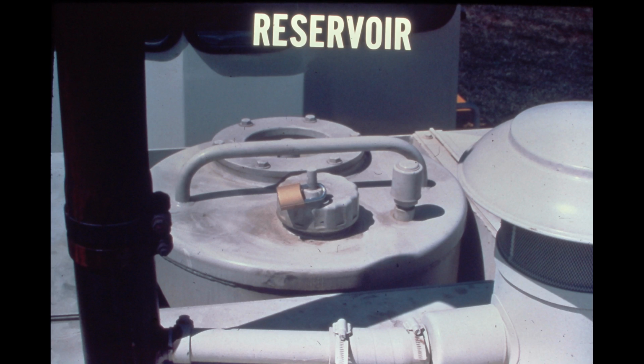The hydraulic reservoir is located directly behind the operator's compartment. Located on the top of the reservoir is the lockable filler cap and vacuum pressure relief valve. This valve limits pressure in the reservoir to 30 psi and limits the vacuum to 0.3 psi. The refill capacity of the reservoir is approximately 35 gallons.